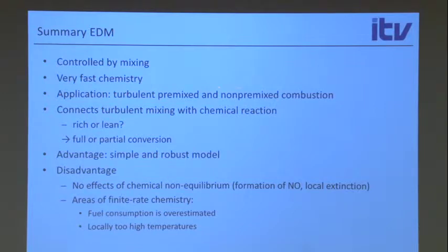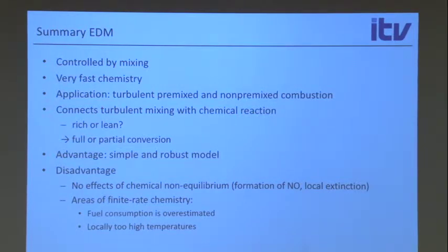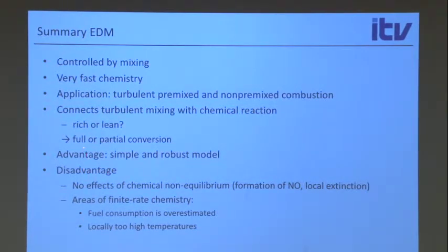It was really developed here for non-premixed combustion. It can also extinguish, for example, or do only partial conversion if the time scale is too short and the chemistry doesn't happen. So once the product mass fraction is 0, then things don't happen anymore.